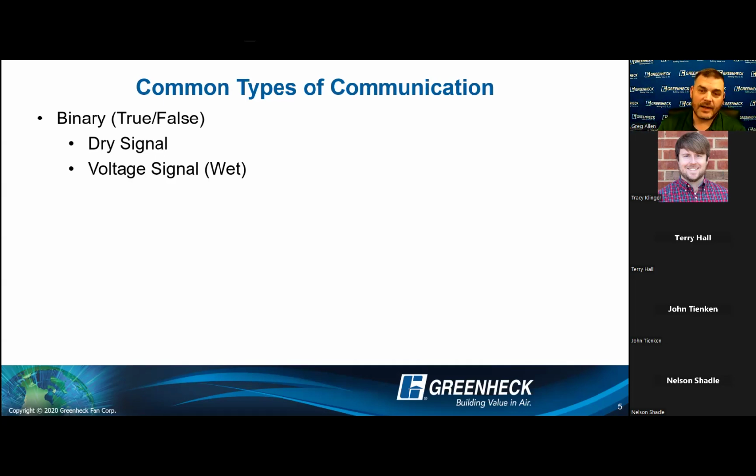But let's say that carbon monoxide detector actually sends 12 volts. Now we have to verify that the contact on the carbon monoxide detector can handle 12 volts going through that dry contact. So you have a step deeper. You may have to look into things. If one's sending power, can the other one take that power? Can it take that amperage and that voltage? And typically right in the IOMs of those products, it will define the terminals and the capacities of those terminals.